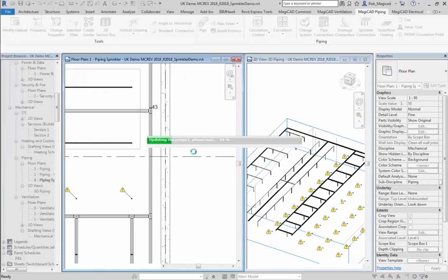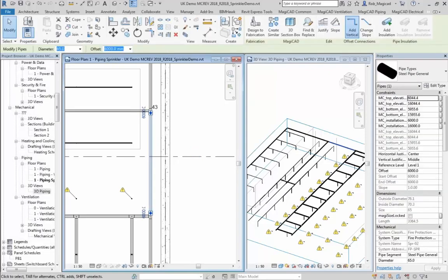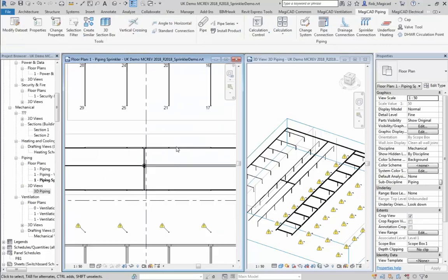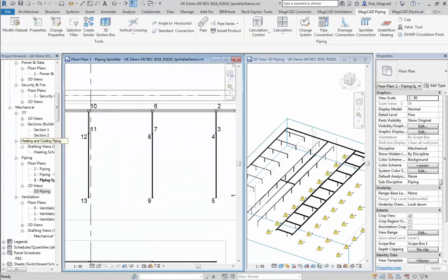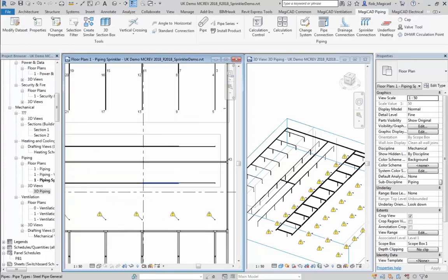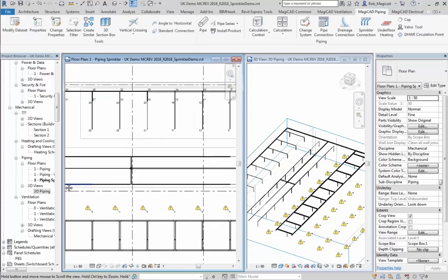And then once you press OK, it will now resize the pipe work, serving all those sprinklers as required in the calculation. So you can see it's now resized all my sprinkler pipe work. You can see there how it's got reducers all over the pipe work now to determine that main pipe size, and so you can see there how that works. And once I've done the sprinkler sizing function, we can now look at some of the sprinkler calculations.